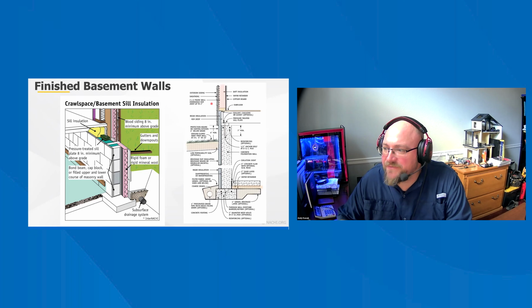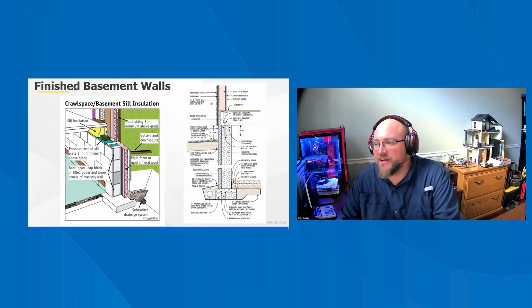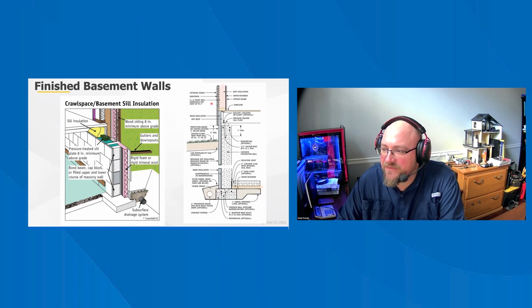sill plate overlaps the upper edge of the foundation insulation, protecting the exterior insulation during construction and providing long-term protection for the exposed insulation. If there is foam insulation installed on the outside of the exterior foundation, look for building practices that overlap and protect the insulation. In new construction, above-grade wood frame wall will typically be constructed of 2x6s that overhang the foundation wall. The overhang can be up to 2 inches. Additional rigid insulation can be added that extends over the entire wall assembly.